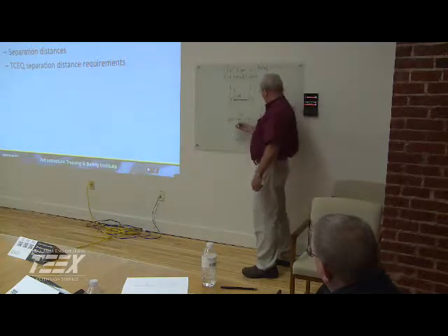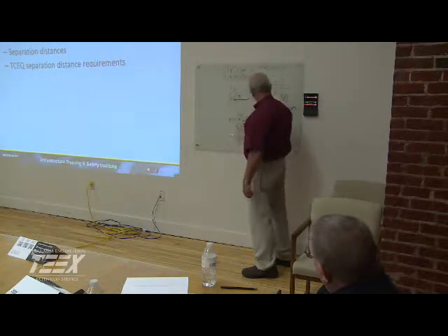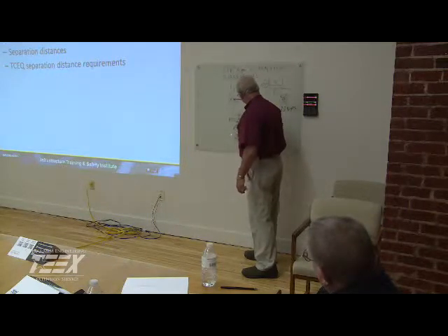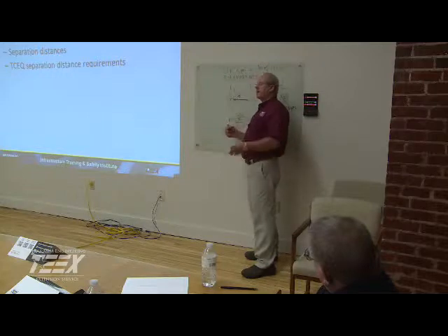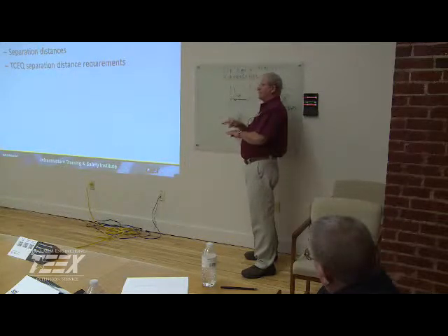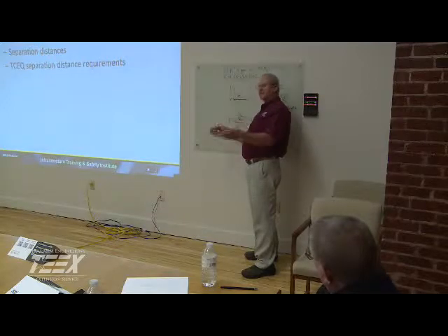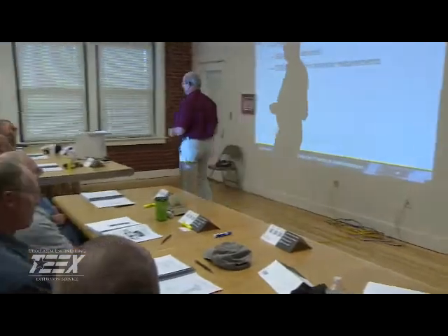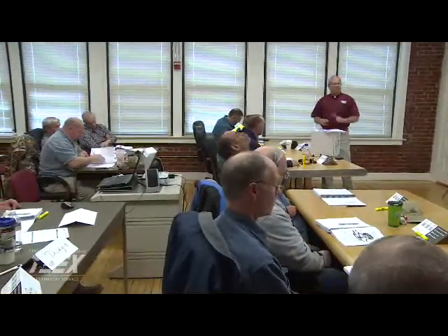Okay? If the distance between the water and the sewer is 2 feet. If it's any closer than that, then you're going to have to encase it and put it in cement stabilized sand to give you more protection. Okay? Things like that. And this is all found in your book, in your own requirements, state requirements.